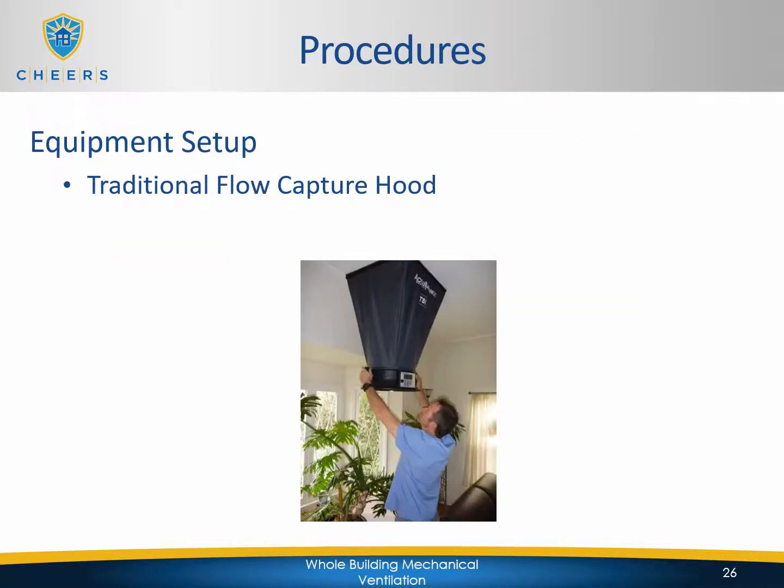And just like the power flow hood and exhaust fan flow meter, you're going to be holding up the flow hood, covering the entirety of the grill that you're about to test.